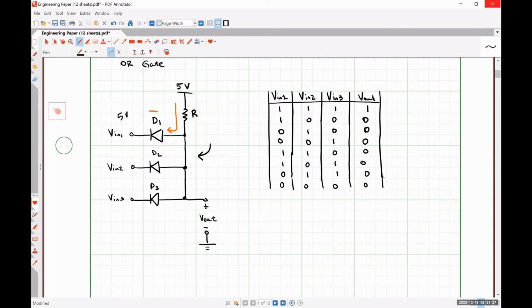Okay. So these are the two different logic gates that we can make with diodes. Simply AND gates and OR gates. So picking one of these, as one group already has, is a fairly straightforward design problem. The only thing that you really need to worry about is when you're using the constant voltage diode model, that's going to kind of skew what you're limiting your input signals to be. And there's some stuff about that in the project assignment description itself.